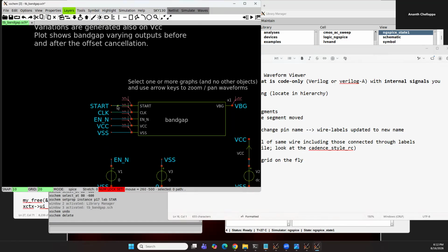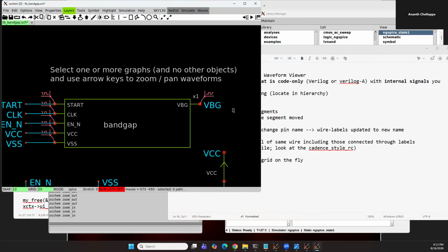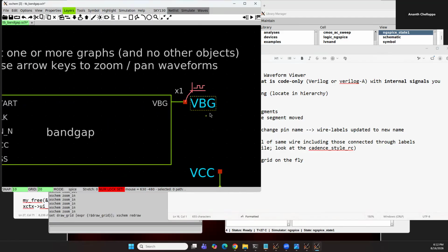And then sometimes it's usually more useful in the symbol view. It works there as well. You see the snap grid is half of the minor grid, right? So if I do Alt up arrow, I'll show you what it did here. Now it's the same as the major grid. Go down one more, and now it's 1/4. Okay, just want to show that real quick.